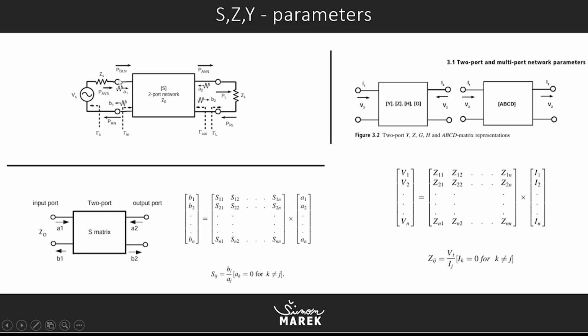So there is our input side and port S1 parameter here and S2 parameter here, and all we need to measure is S21 parameter, which is S2 is here and S1 is here, so it is gain parameter for our amplifier. Sometimes you can only measure reflections, which is S11 parameter, which is here, and this is all we need to know how to plug our VNA.